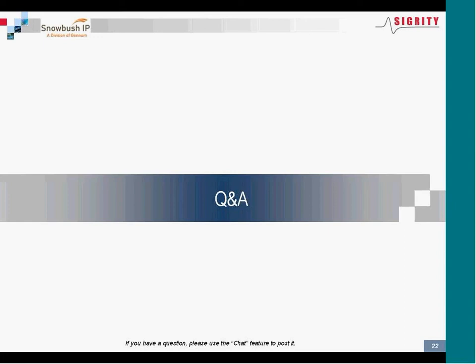But the other answer is that the way the models are currently written, there is a training file that both AMI models have to point to, and the simulator won't treat it as a valid back channel system unless they're both pointing to the same training file. That training file basically just contains information that says, this is how we want to run the back channel, here's some of the details on how to do it. But it won't be recognized as a valid system without that.